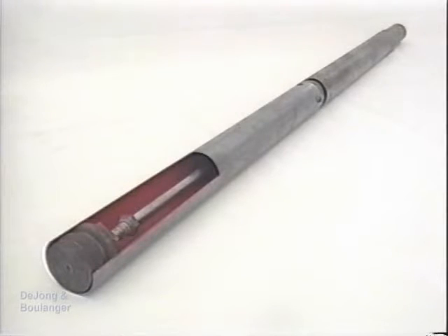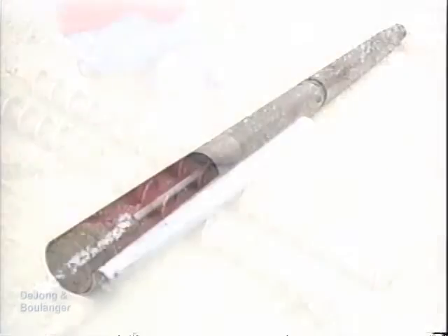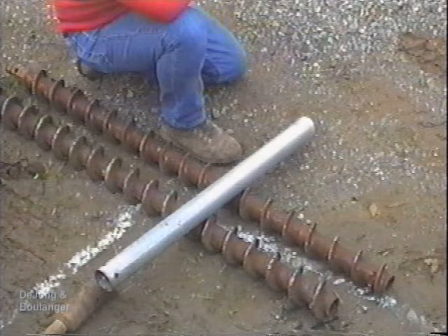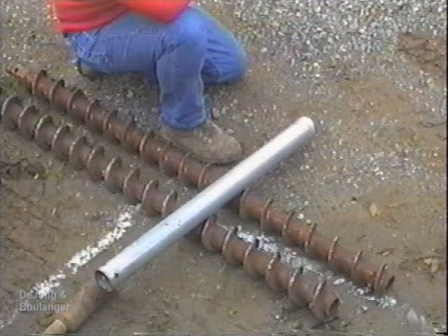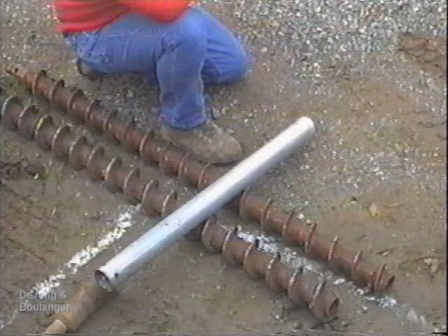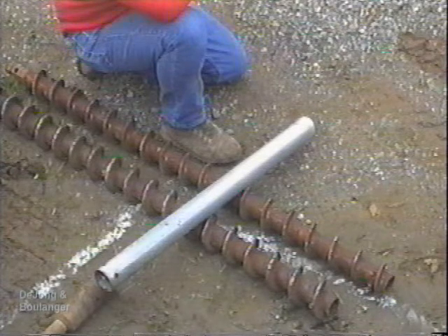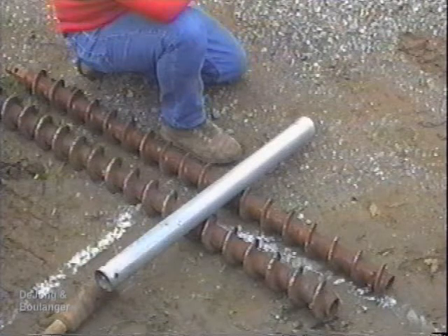Initially, the presence of the piston prevents soil from rising into the tube faster than the tube's penetration rate. Later on, downward movement of the soil sample is resisted by a vacuum that develops between the piston and the top of the sample. After the sampling tube has been advanced, the piston is fixed in its new position with respect to the tube. Both elements are rotated to separate the sample from the underlying soil, and the piston and tube are removed from the hole.